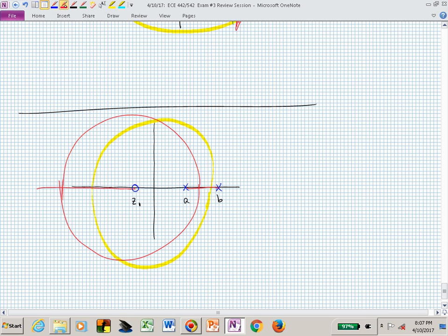And what would you do? You could pick those, and now I might say pick closed loop poles to locate them at the squares. Now what's your settling time, percent overshoot, and peak time? You can get that from the squares. You find their radius away from the origin and their angle, and now you back out those performance specifications from that complex pole location. And it's all coming full circle. No pun intended.